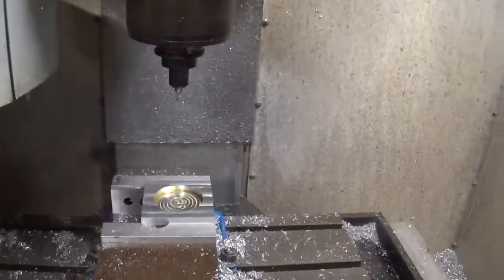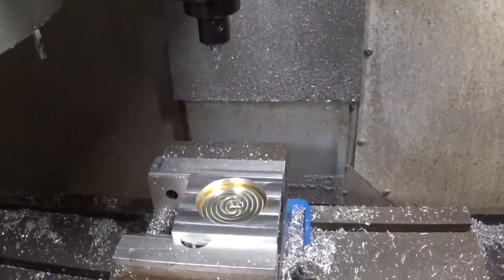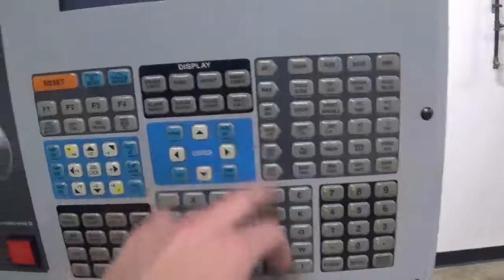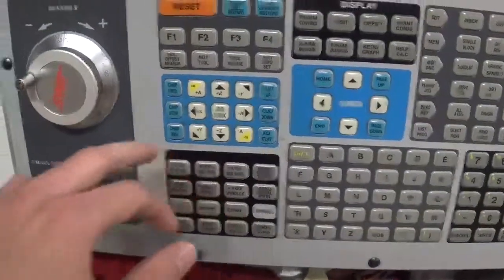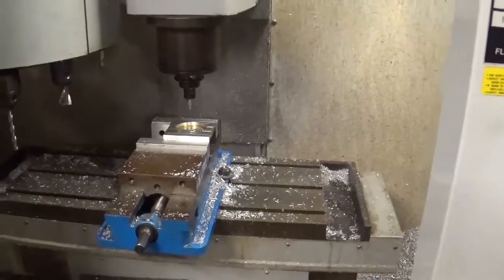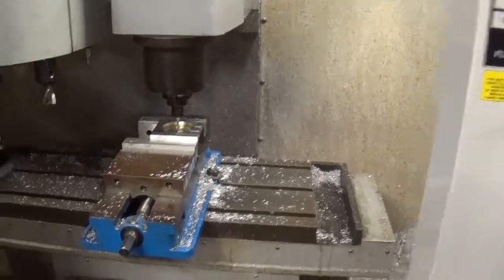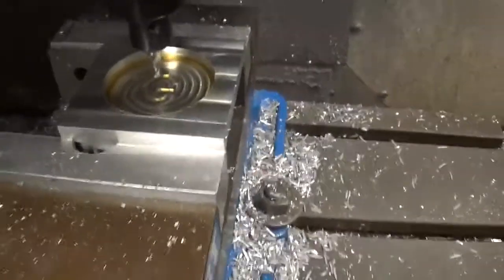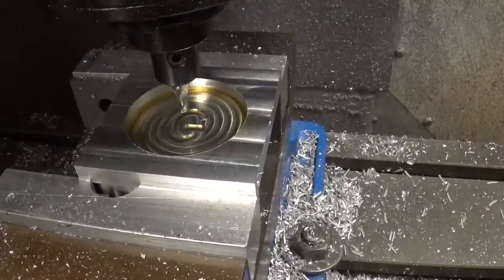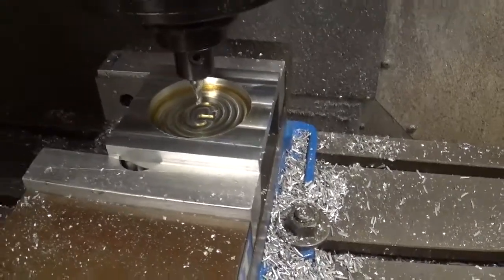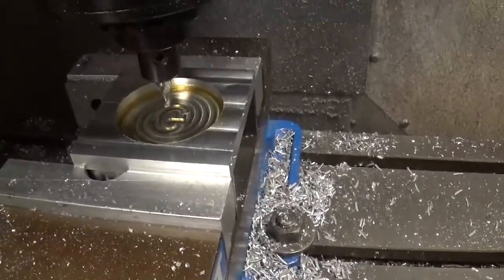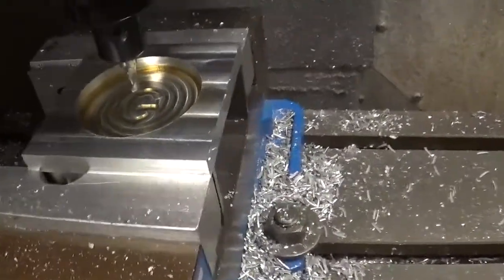Alright, so you can see I did a little bit of movement. Can't really tell if this tool is in the center here, so I'm going to hop over to hand jog here, moving the Z, and I'm just going to move down slowly. And if you look, I'd say I did a pretty good job setting up my work offset here. It's not guaranteeing anything that you have it down to the correct position down to a couple tenths or anything like that, but it just gives you some reassurance that your tool is where it's supposed to be.